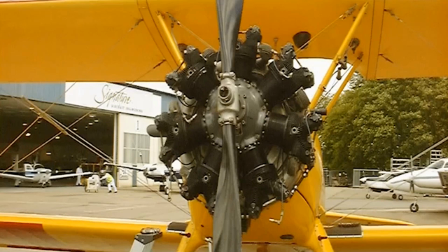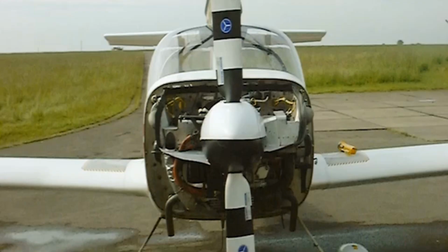Adjustable pitch propellers are propellers which can have their pitch adjusted on the ground by mechanically resetting the blades in the hub. In flight, they act as fixed pitch propellers. Two-pitch propellers are propellers which have a fine and coarse pitch setting that can be selected in flight. Fine pitch can be selected for takeoff, climb and landing, and coarse pitch for cruise. Two-pitch propellers will usually also have a feathered position.